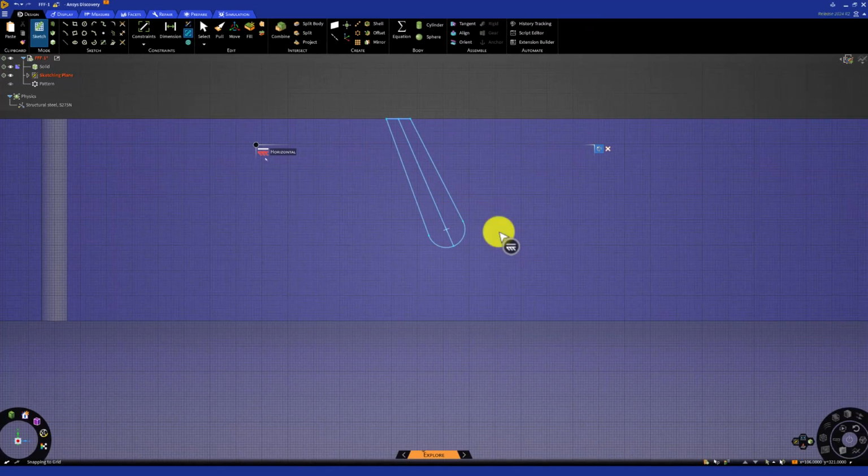This constrains a given sketch element to be horizontal. Because of the chosen orientation of our sketch relative to the origin coordinate axes, to make this line lie along the radial direction, we must constrain it to be horizontal. So click on it to constrain it.